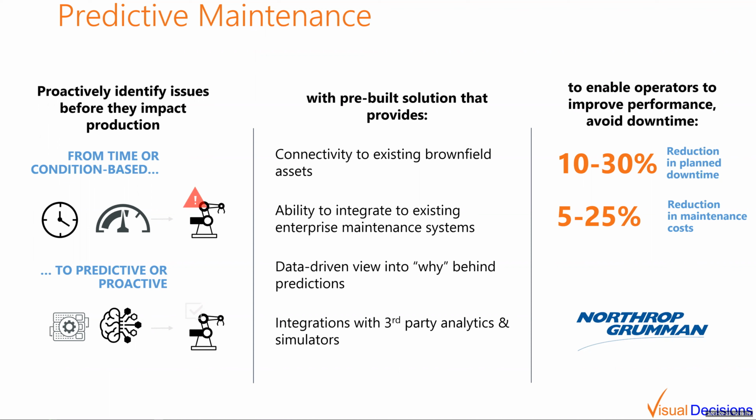And so the advantage here is that essentially, in the past, you had various choices. You could either do PM activities at a set interval, or you could look for big changes in the condition of the equipment, or you could basically just run until failure. And for some things, running until failure was actually the right choice because it didn't have any catastrophic consequences. It didn't cause long downtimes, and it was something that you could just make a quick change and keep going.